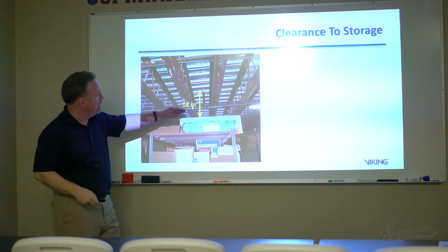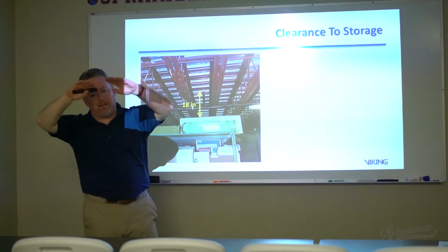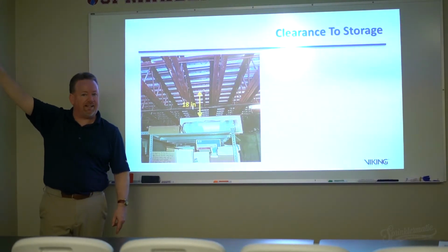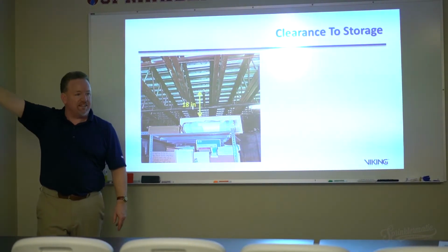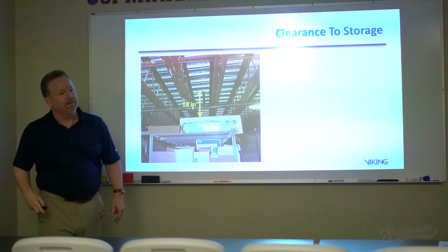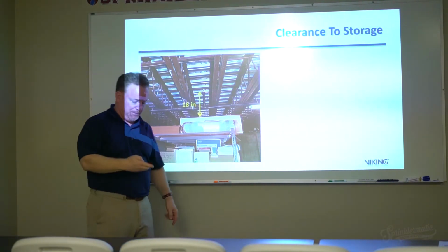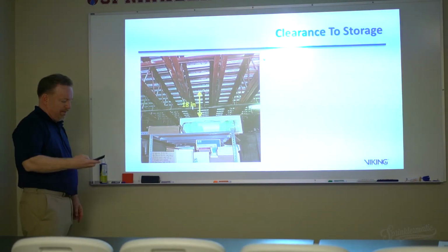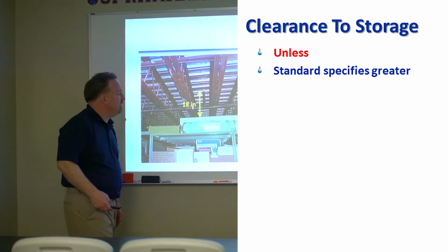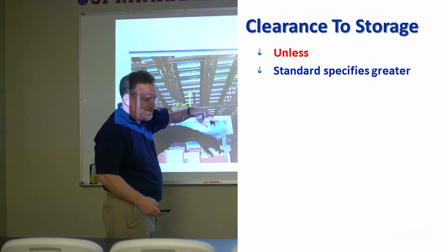Because remember, this 18 inches is spray pattern development. If my spray pattern is not trying to get to the other side of the wall, then this does not obstruct spray pattern development any more than a wall would. Racks in here, yeah. If it's out here, you've got a problem again. So the standard specifies anything greater than 18 inches, and that's ESFR.